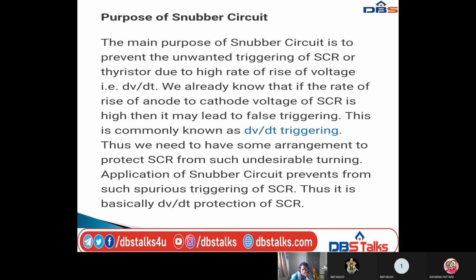Thus, we need to have some arrangement to protect the SCR from such undesirable turn on. The application of a snubber circuit prevents such false triggering of the SCR. Thus, it is basically dV by dt protection of the SCR. So why are we using a snubber circuit? To control unwanted triggering. Here we have to protect against dV by dt triggering of the SCR.